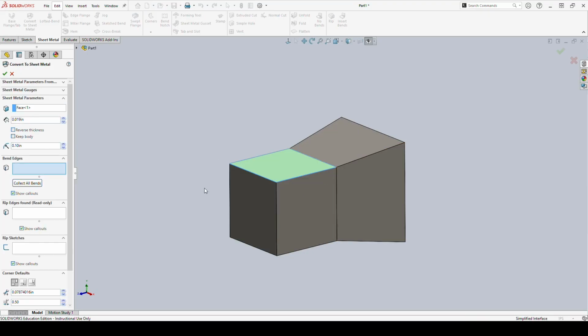So when I go in, I want my vent, I'm going to go ahead and set this top face to be my main piece. I'm actually not going to select this face at all, nor am I going to select the face that's on the other side here that I'm not seeing, because if this is like an air conditioning system that is now opening up, meaning widening here, what you're going to see is there's going to be air flowing through here. So I don't actually want anything on this face. And what I can actually do is make it such that there is nothing on that face.